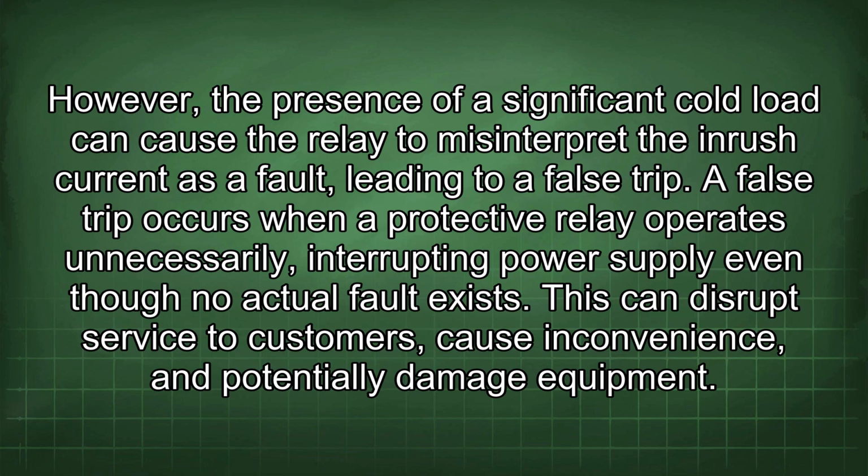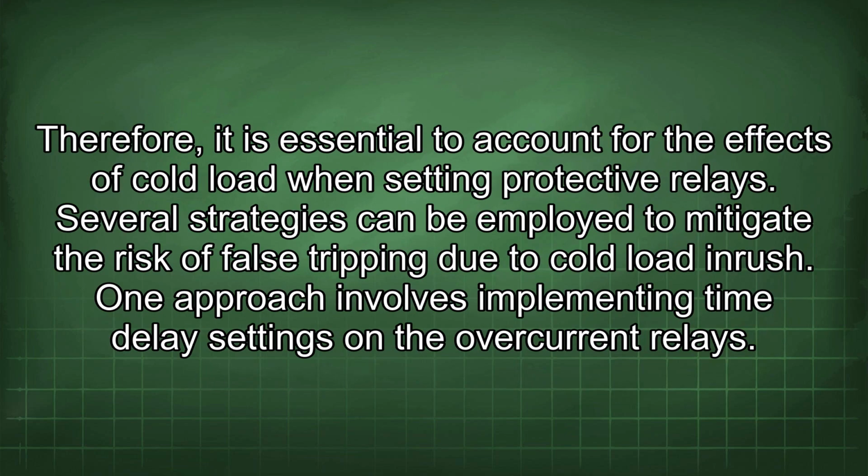A false trip occurs when a protective relay operates unnecessarily, interrupting power supply even though no actual fault exists. This can disrupt service to customers, cause inconvenience, and potentially damage equipment. Therefore, it is essential to account for the effects of cold load when setting protective relays.